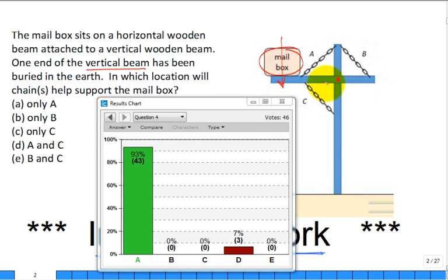Even if you put a couple nails there or something, it's still going to want to rotate around that point, even without any chains. So if it starts to rotate around that point, if you look at the distance between this point and this point, for chain B, it would be brought closer together if it moved in that way. Wouldn't these 2 points come closer together?